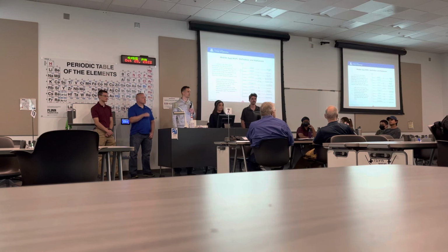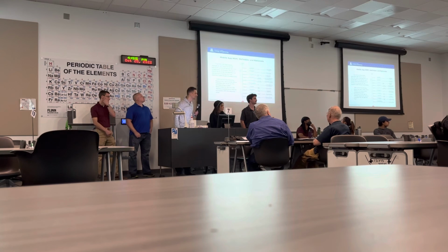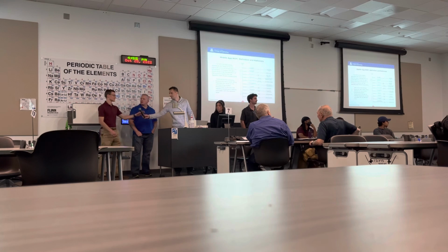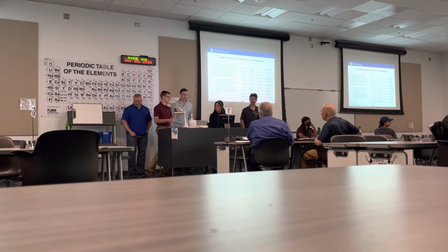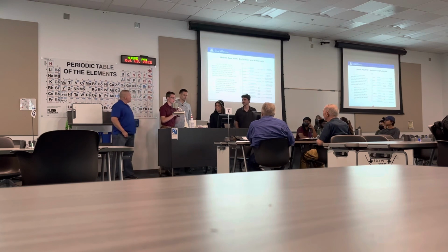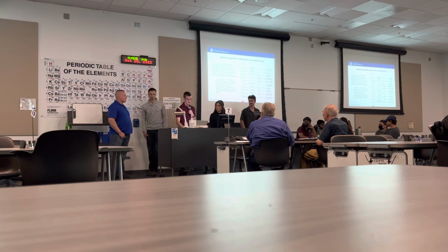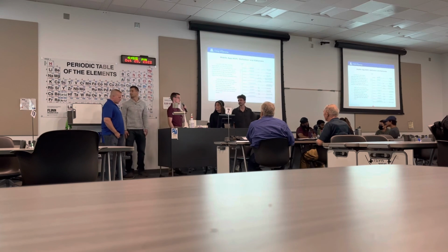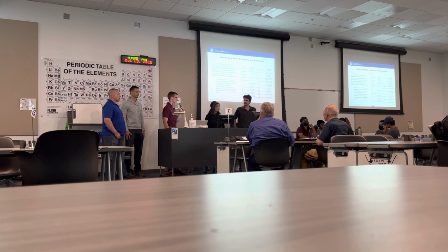Do any of the teams have questions for Lucy? This is your chance. I noticed you mentioned a specific battery. I believe it was like the CR1225. Is there a specific reason you chose that battery over others? Oh, you're talking about the coin battery probably. Yeah. So I chose that one because it's a 3-volt battery right now, and that's what we're shooting for. I just really wanted an image to give you an idea of what we're looking at. It may not necessarily be exactly that battery, but it's going to be a 3-volt system.